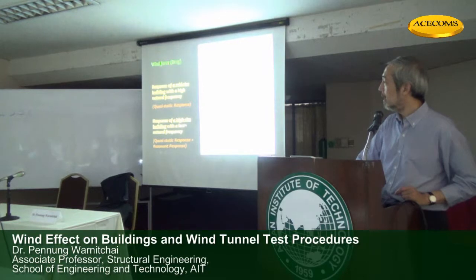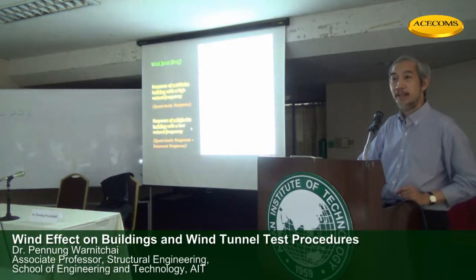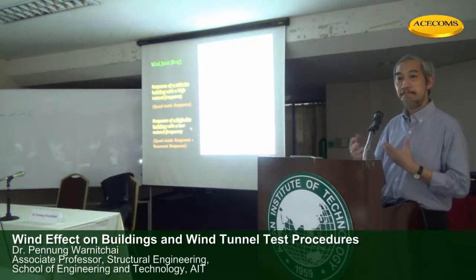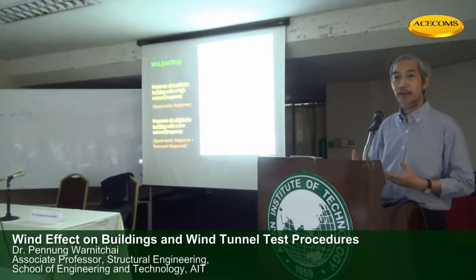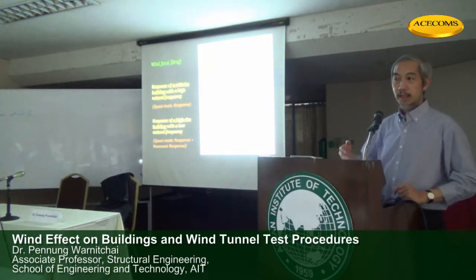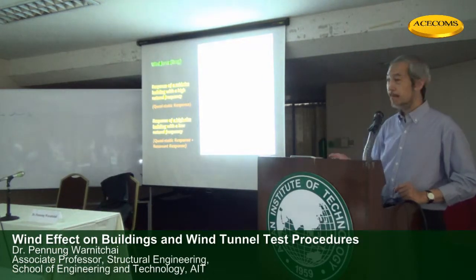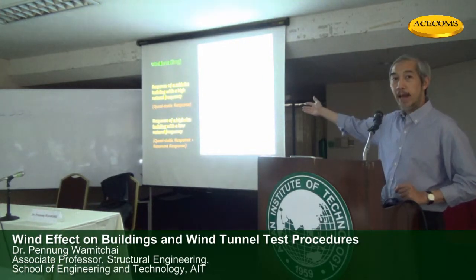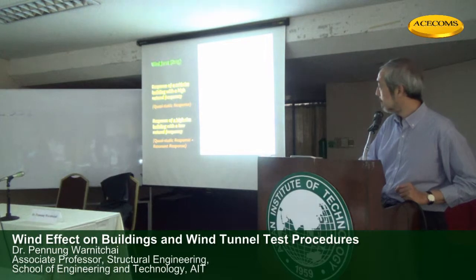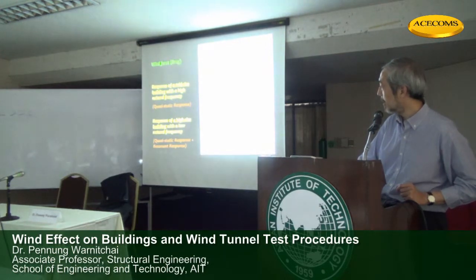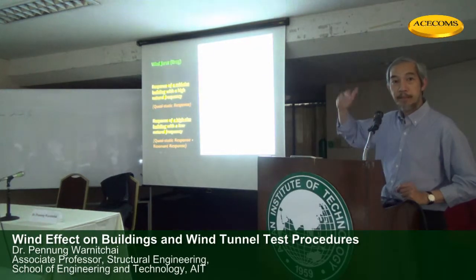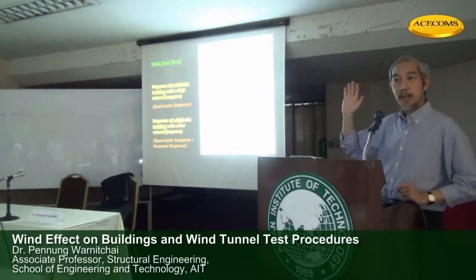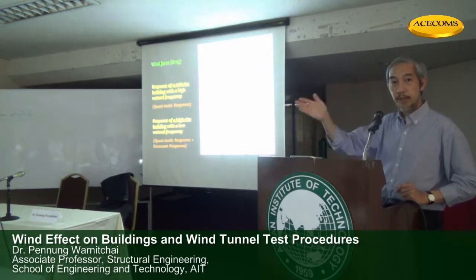But when you have a high-rise building with low natural frequency, which is typical for tall buildings of 30 stories and up, you have an additional component. You can see this fluctuation on top of the quasi-static response: vibration, mostly in its fundamental natural frequency.